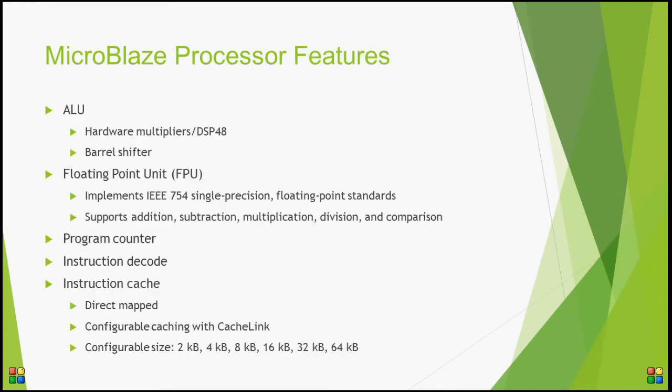MicroBlaze has an ALU that can be optimized to use the dedicated DSP slice in its construction. It also has an optional floating point unit that supports common arithmetic functions. MicroBlaze also has a program counter, instruction decode, and optional cache functionality.